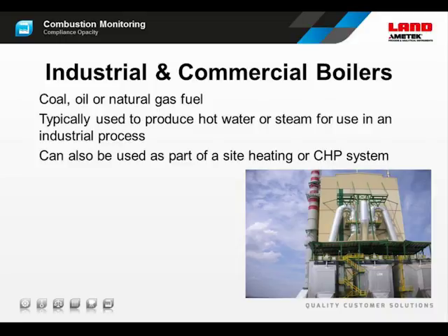Larger industrial boilers also need to report opacity. In the US, typically anything with a flue of 3 feet or 1 meter in diameter or larger will have an emission limit value. And some smaller processes also have to report opacity. We actually installed a 4500 Mark III on an incinerator flue which was 10 inches diameter, 25 centimeters. So that's the smallest flue we've ever measured on.